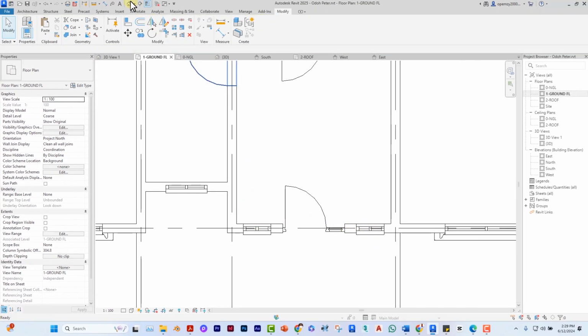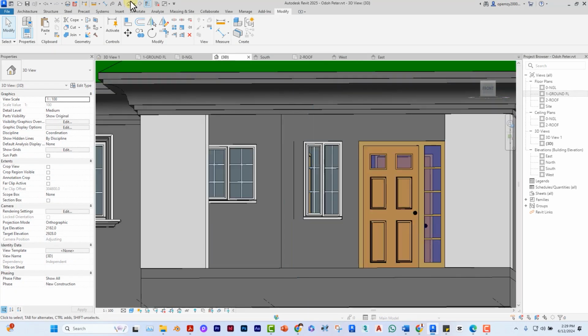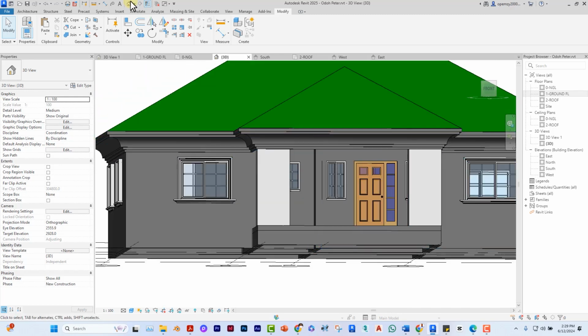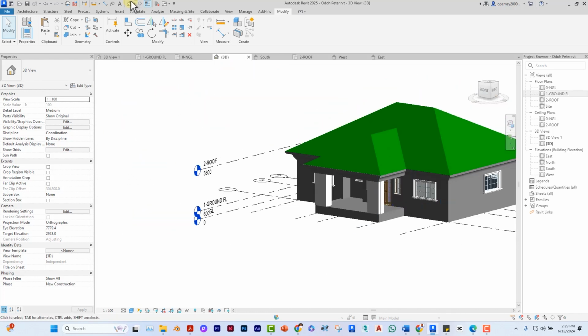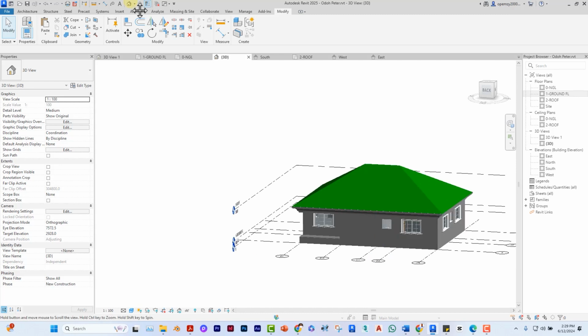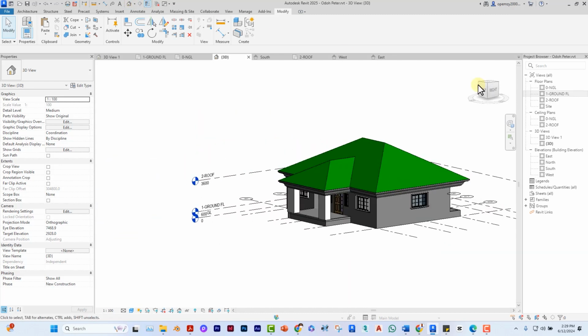So once you do that, you discover that, say, we have tinier windows, and I can place window hoods all around this. Or I can decide to just place one gigantic covering of a hood around this window and doors. But this is how you do it. I might not necessarily bother there because they are recessed walls. But basically, this is how you go about creating window and door hoods.